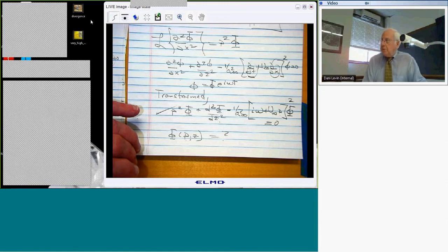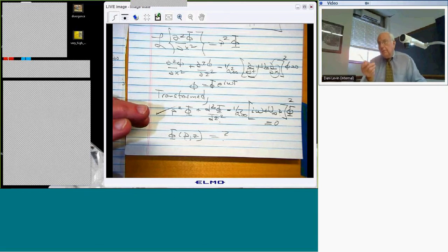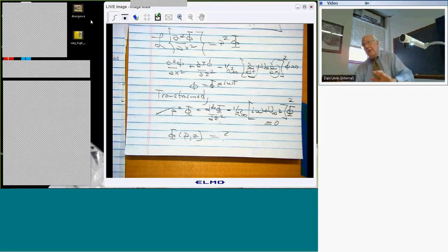In incompressible subsonic flow, there's an analytical solution in terms of these Hankel functions for the two-dimensional case, not for the three-dimensional case. So 2D incompressible flow has a more or less analytical solution due to Theodorsen, the famous Theodorsen. And the supersonic flow case, so many people worked on it, it's not quite clear who actually did it first, so it doesn't have a name associated with it. But once you go to 3D, it'll be a numerical procedure. And then in transonic flow, unless you're going to use slender body theory for low aspect ratio wings, you're going to go to a nonlinear PDE, and that gets substantially more complicated.